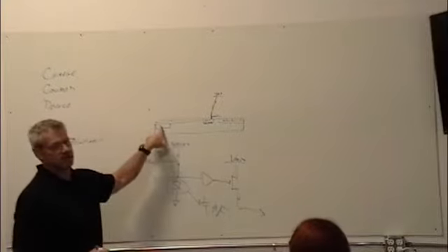Now understand that the CCD process is a different process than the CMOS process. So if I want to build a CCD that's got all the readout electronics built into it, that's hard. In fact, I'm not sure there's very many that are still doing this at all. I know Kodak did a little bit with some of theirs, just the basic stuff.